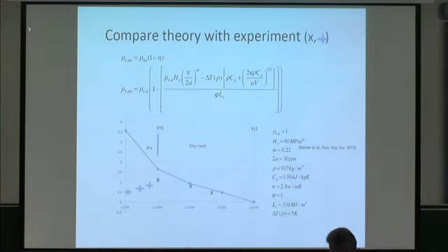What you see here then is the blue curve is the theory, putting again one more time parameters that one measures from bulk material, assuming that, well, they're the only numbers we have, and so we use them, assuming they apply to the asperity. And you see here then that there are these regimes, one more time. The dry regime, this model applies not to the dry regime, only to the dry come wet regime.